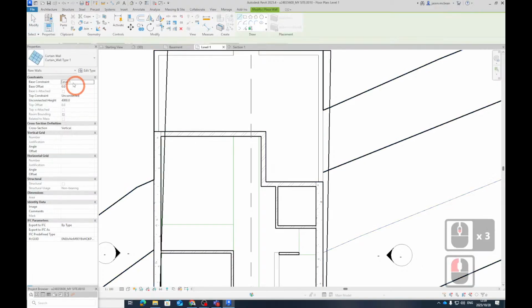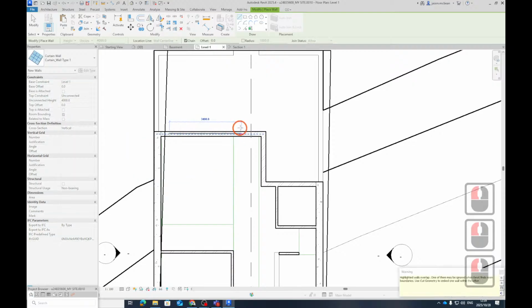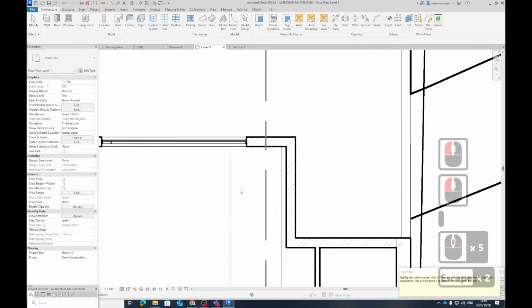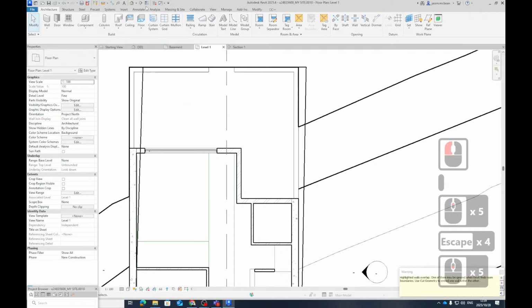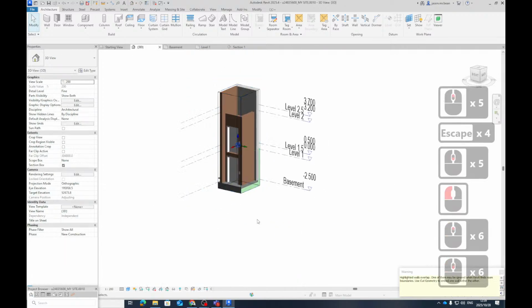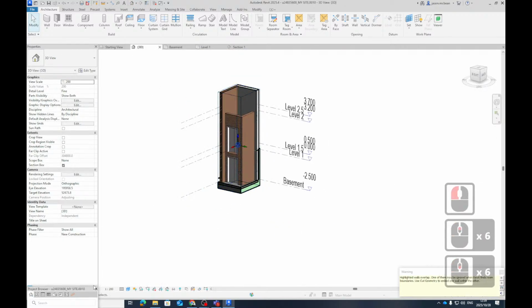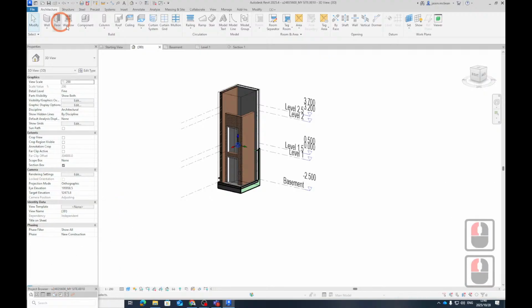Okay. Wall, before I go any further there, watch this. See what it does? It opens the wall. It actually embeds it in the wall. So this is how we can use windows. If this has happened in your 3D view, to reset your 3D view... oops, I've done something here. I've dragged this out by accident. I've stuffed up my view.